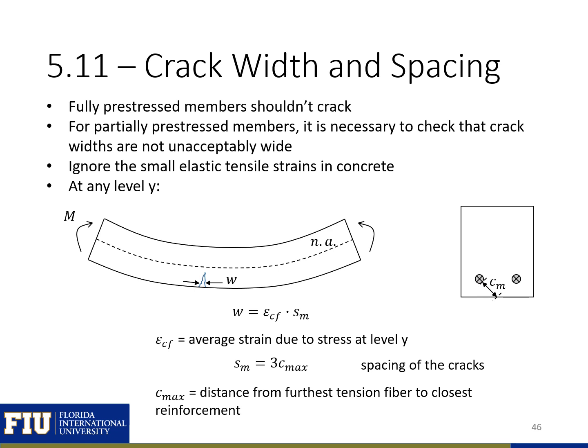Next, we'll briefly discuss the relationship between crack widths and spacing. We talked about this already for axially loaded members, and there's a similar relationship between the width of the crack and the spacing of the crack. You can see that in general, if you let cracking happen, then the closer spaced your cracks are, the smaller the width of the crack is.